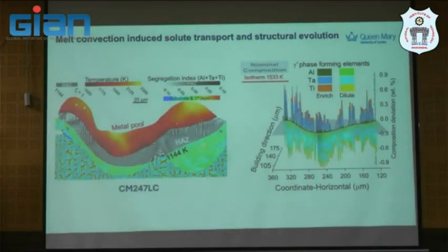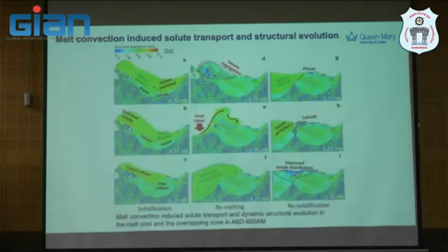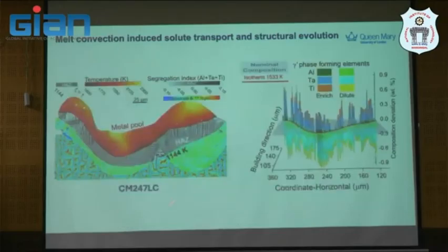What we see, what does it mean by that? If you see here, this is the melt pool, you see with the porosity as well. In CM247, if we move a little bit to the highly segregated kind of material like CM247, we talk about the hafnium profile. Again, this is coming from modeling only. So you will see this is the substrate layer and then the second layer here. And then the metal here is actually the melt pool, heat affected zone, solidification progress here,